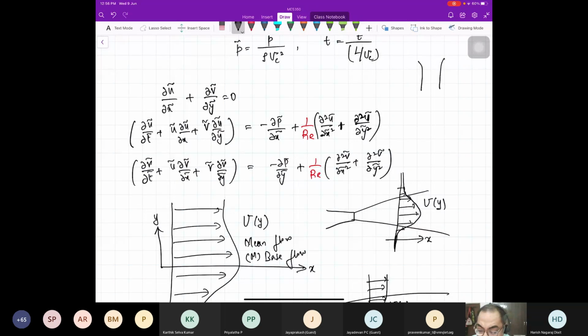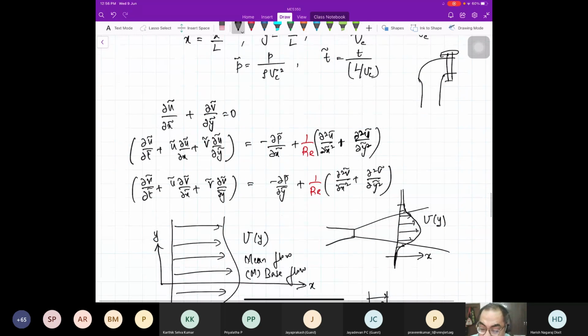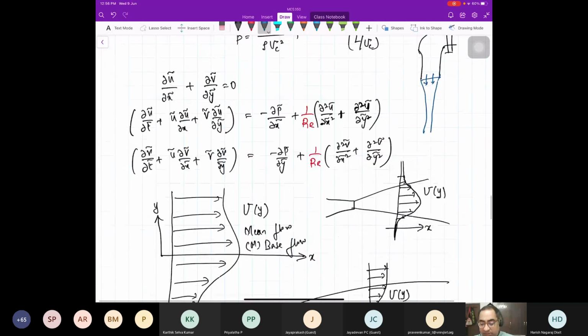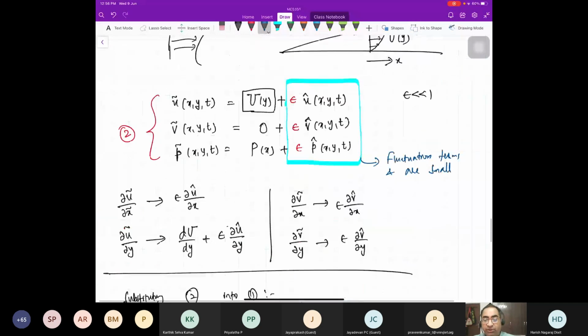Okay, this is a water tap. If you open the tap, then you basically get a stream of water, right? You make an estimate of what the velocity of this is. Take a typical velocity of 1 meter per second. Typical diameter of the tap is, let's say, 1 centimeter. And you use the viscosity of water. You will see the Reynolds number is in the thousands. Even for this system, the Reynolds number is so large you can ignore viscosity.